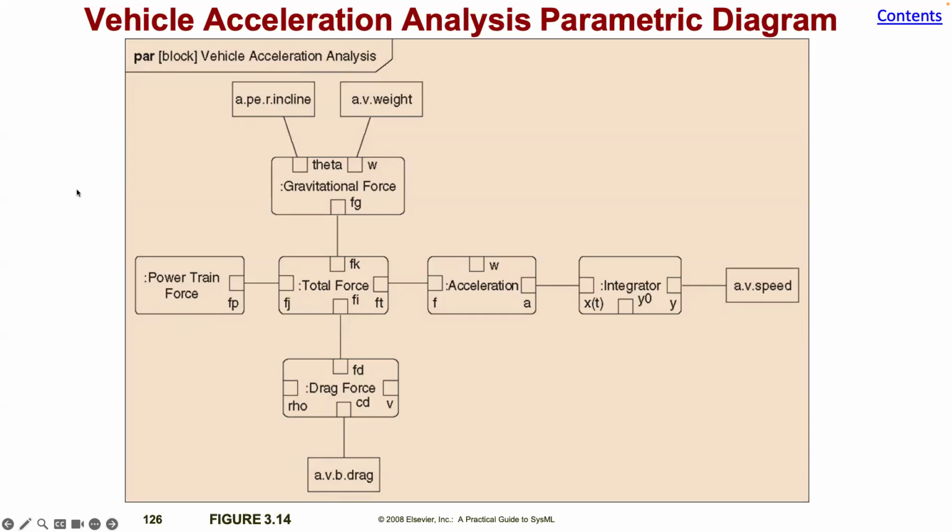One of the things I've taught a couple of times is kinematics, doing physics courses. And so with an incline, you have to think of your trigonometry. Gravity is always going to the center of the earth, but if you're at an incline, it's going to affect what the gravitational force is in the direction of the road because you're not on a flat surface. And so we have all of the things that we are familiar with, the powertrain. We're looking at the force that's there, and how it is going to contribute to the total force that's available for the locomotion of the car.